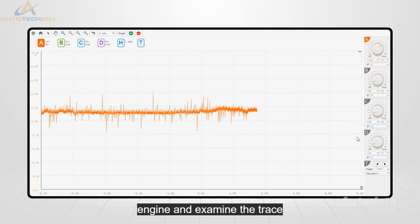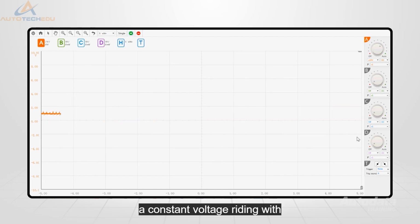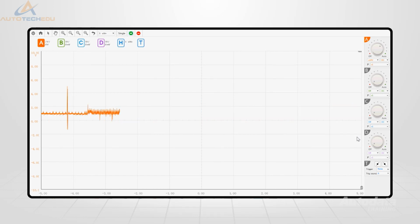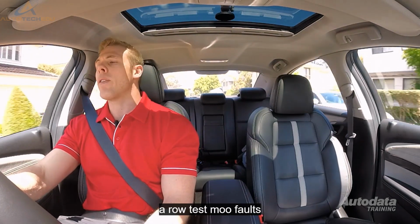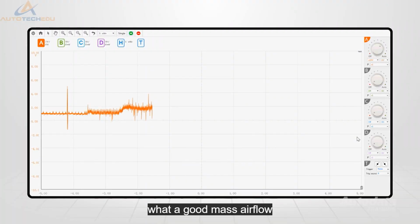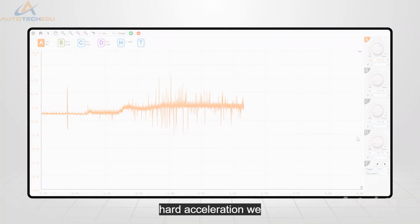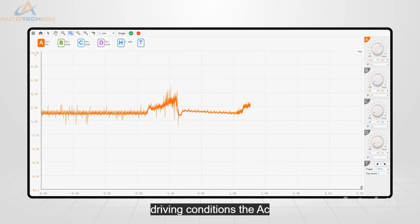Start the engine and examine the trace. At idle, a correctly functioning trace should look like this. There is a constant voltage reading with no major changes. Capturing a trace while performing a road test may show faults under different load and engine speeds. This is what a good mass airflow sensor trace looks like under hard acceleration. We can see the voltage rise and fall according to the driving conditions.